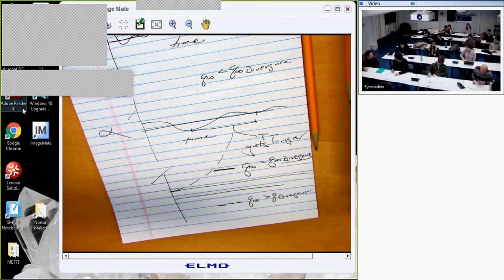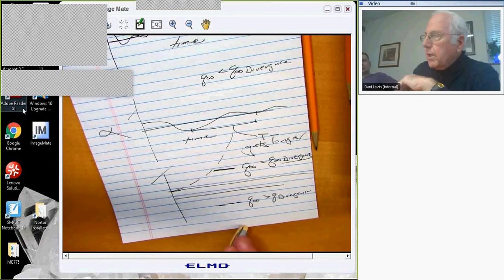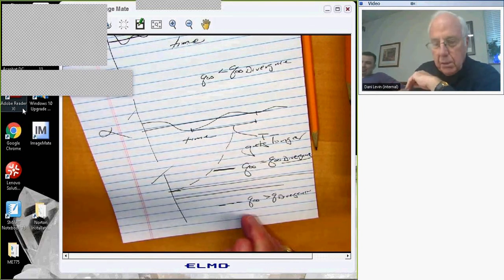Since divergence can be analogous to a buckling effect, which a buckling force has, but for divergence to happen, it was said that you have a force which is acting at the center of pressure. What is causing the beam to buckle and not bend? What I'm trying to ask is, at the unsupported end, what is the force which is keeping it from not deflecting? So you have a buckled profile. Oh, you're saying if I have a real airplane, when it has a tendency to diverge, it really won't go off to infinity, but it'll buckle at some finite deformation. Is that your question?